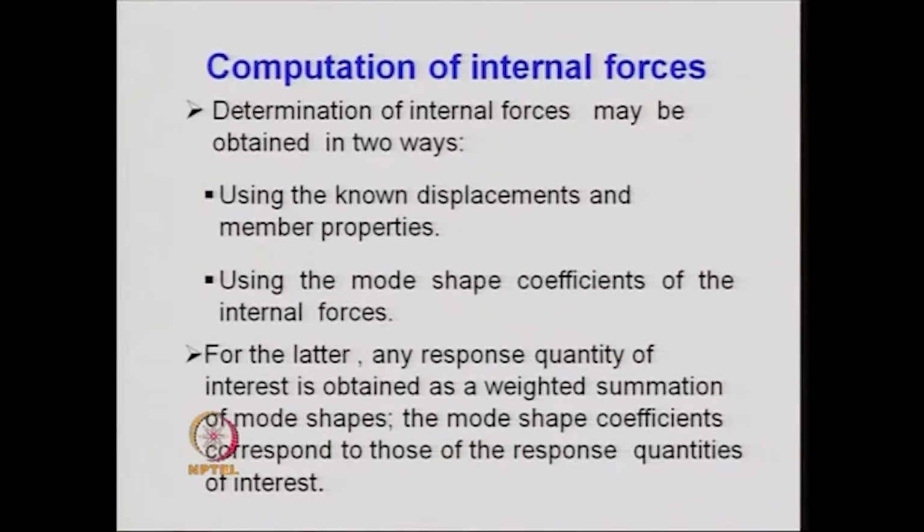In that, we perform two analyses: one, a quasi-static analysis in which we consider the contribution from all modes, and the other, a dynamic analysis in which we need not calculate the generalized accelerations and generalized velocities. By knowing the generalized displacement itself, we can obtain the contribution coming from the dynamic analysis, and that contribution may be considered only for the first few modes, and we can sum them together.